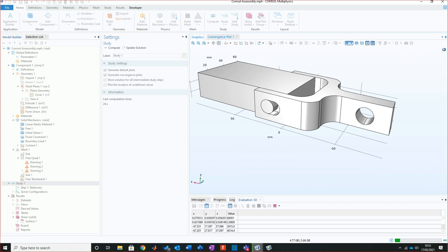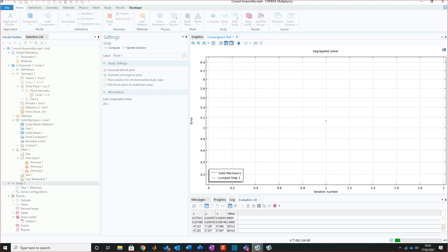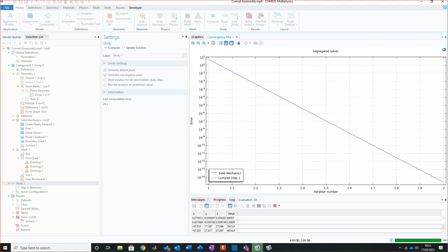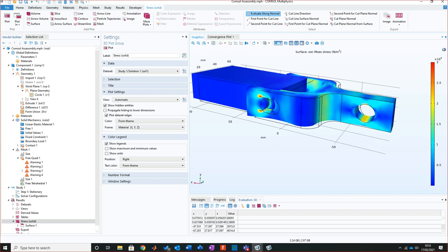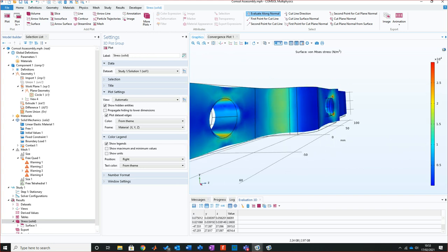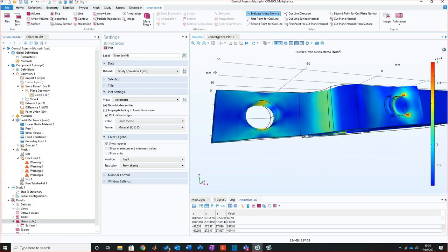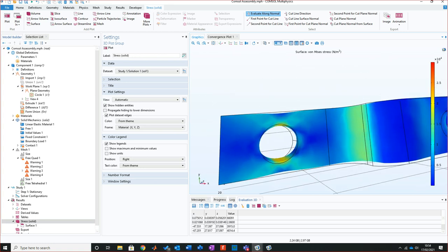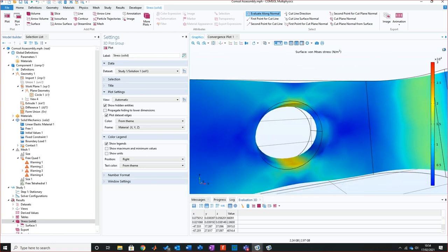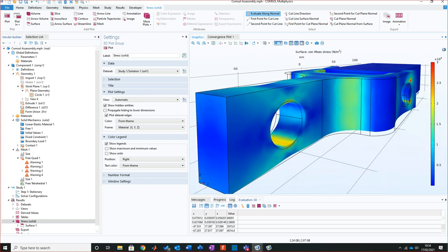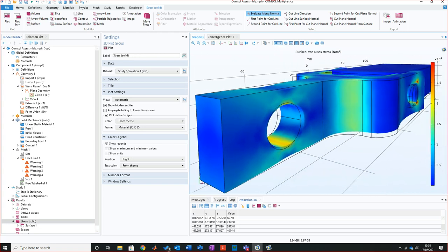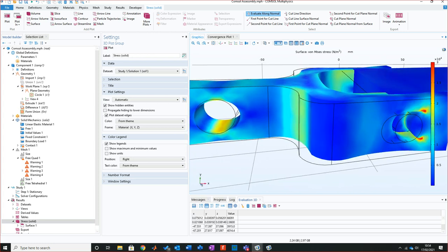When this runs through, what the convergence now does is it will plot the result, the solid mechanics against the lump. Oh, there we go. Already done. And you look here, and interestingly, because this is structural steel, it deflects that little bit more. You've got that higher deflection, but what we've actually been able to do is drop the weight. We've been able to drop that material.